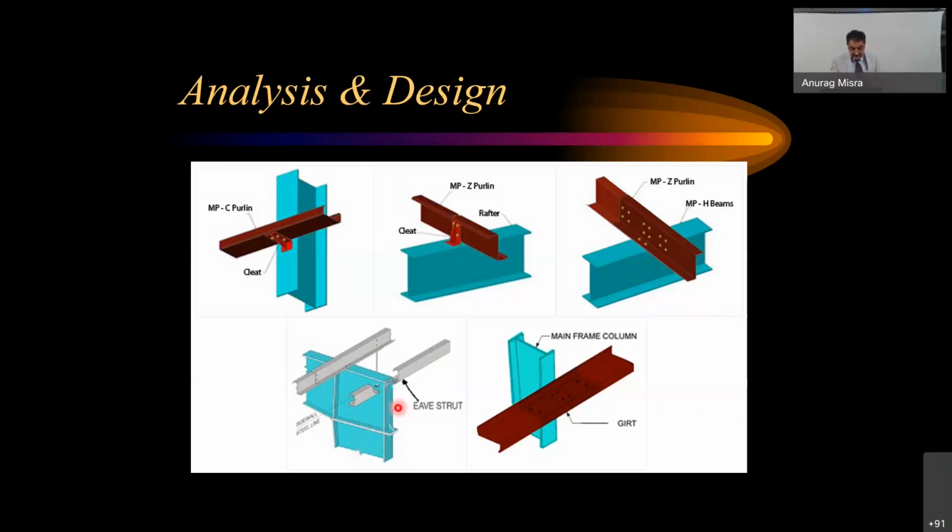So like you can see the column and beam. You have here the connection plates and the bolting is done. Similarly, there are holes here which you can use for fixing the purlins on top of them. So no welding is allowed, only bolted connections. You can go with that and provide the structures at a faster pace.